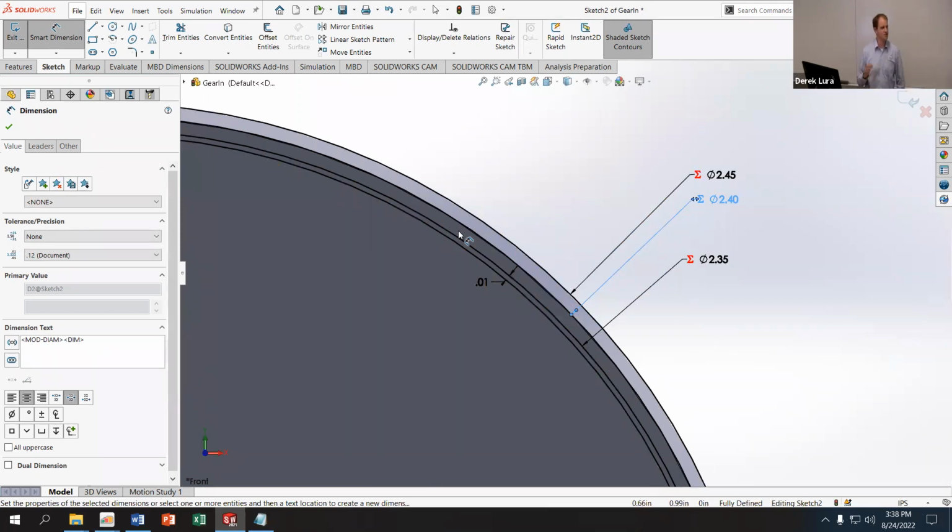And what I'm going to do is turn these into center lines, so that they are just references that I can use as I draw my gear profile onto this part. And really the reason I'm doing this differently than when we did it last time is I want to try to use the same profile for multiple tooth cutouts, but I don't want my cutouts to actually change the geometry of these lines. So hopefully that'll make sense. I'm going to make these all construction lines.